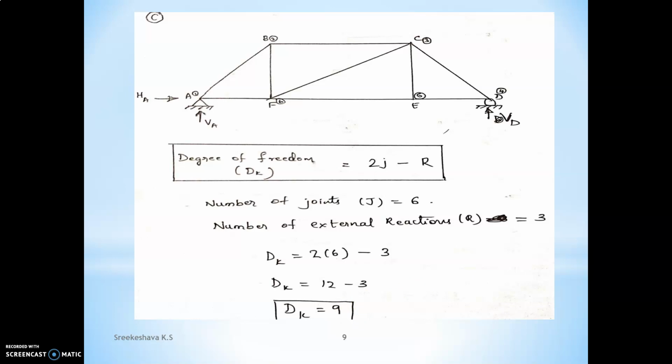Clear? So in this particular tutorial, we discussed how to compute joint displacement or degree of freedom at each joint, and for the whole structure it is the sum, which is called the degree of kinematic indeterminacy. And we also solved some special structures with imposed conditions like internal hinges, and also a truss, using some empirical relations. I hope you are getting how to solve these questions in the easiest way.